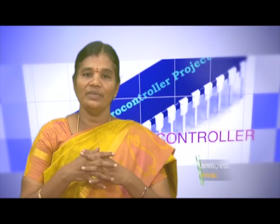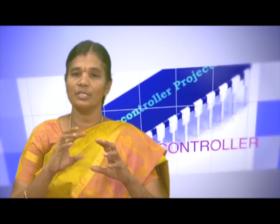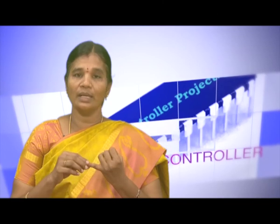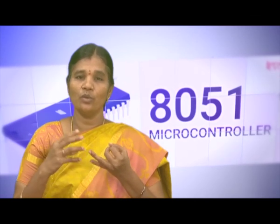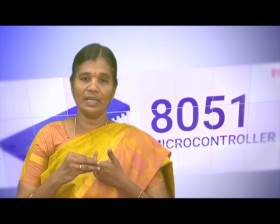In today's session, we have discussed the format of the SCON register, and how to transmit a number or specific characters. For this kind of transmission, first you have to know how to activate the timer mode, because we have to calculate the baud rate and load it in the TH1. To use the TH1, we have to activate timer 1. That's why we use the timer mode and the TH; both are for giving the baud rate. If there is no baud rate, there is no need to specify this. Then you activate SCON, then we give the SBUF value, whatever you want to transmit or receive, which should be loaded in the SBUF. Via the accumulator only we are performing this. So you activate SBUF, then transmit it.